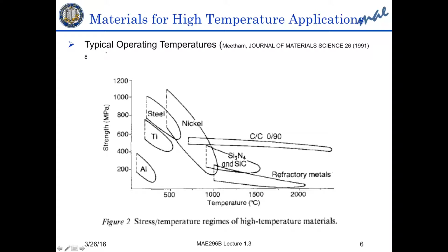Steels are higher than the titanium, but still limited to 500 or 550 degrees centigrade if we sacrifice some of the strength of the steel. And then we move on from steels to nickel-based super alloys, and that's a whole large group of alloys, the strongest of which can work at lower temperatures. The highest temperature would be reserved for alloys that have relatively lower strength. So those that can operate at 1,000 degrees centigrade would have to be designed to handle lower strength levels.